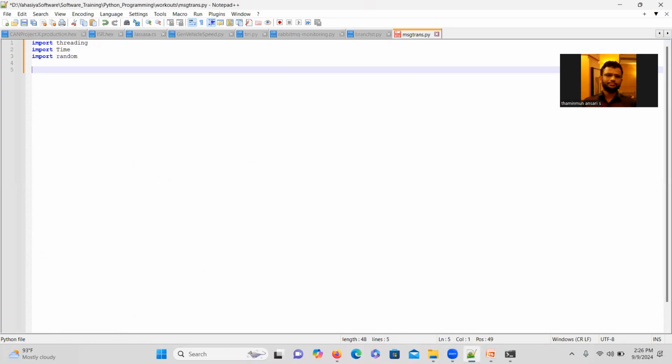Okay, after that, what do we have to do? First thing is we have to define a CAN packet, right? As the vehicle speed is involved, we can call that packet BCM info, because usually BCM transmits the vehicle speed. Then we generate a dictionary for the CAN packet.